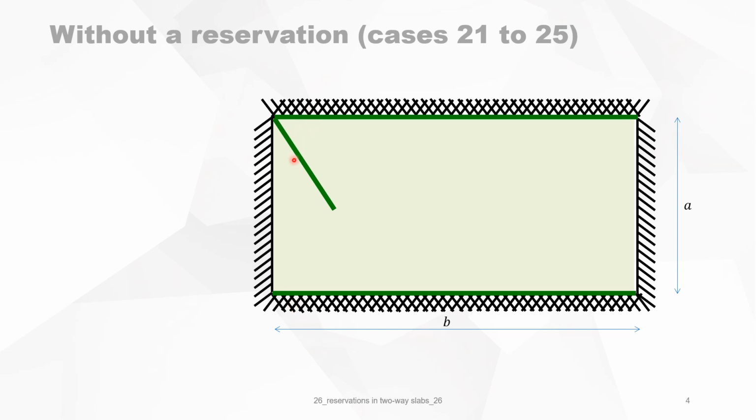We use the 60, 30, 45-degree rule. So we draw from the cross sections of the two axes of rotation. From this point on, over an angle of 60 degrees, we draw the yield line. We do the same in the opposite corner. And then we connect the two intersections. So now we have the yield lines of the slab in ultimate load, and each part of the slab can now move as in a mechanism, and the axes of rotation are the four sides of the slab.